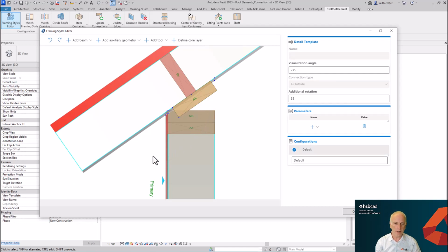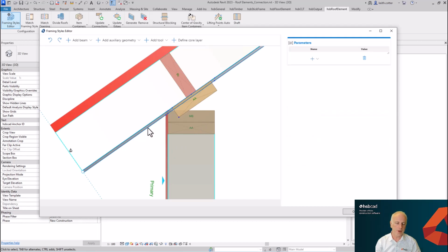So all we have left now to do is one last step, and that is this particular sheet here is currently running right through into this beam and out the other side. And what I want to do is cut back that sheet maybe to these 2 points here. You could obviously add additional points as well if you wanted to control it, or I could even add an offset line from an edge here and control how far away I want the offset line. But I'm going to keep this quite simple, and I'm going to add a sheet cut to this